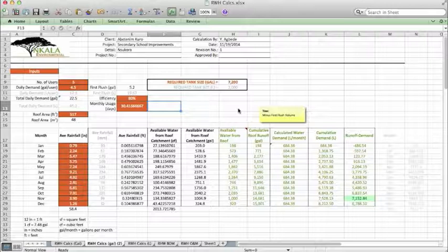So where can you go to find data on your average monthly rainfall? You can go to the National Weather Agency if one exists. You can go to perhaps the Ministry of Agriculture. Sometimes the military will have that type of information. You go to airports, they often keep records of weather, things of that nature. And like we've always said again, if all those things fail, you can go to an elder in the area and get insights on the amount of rainfall for the various seasons.